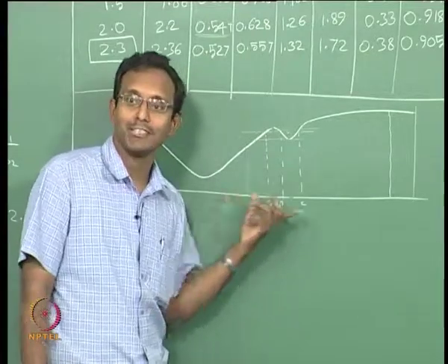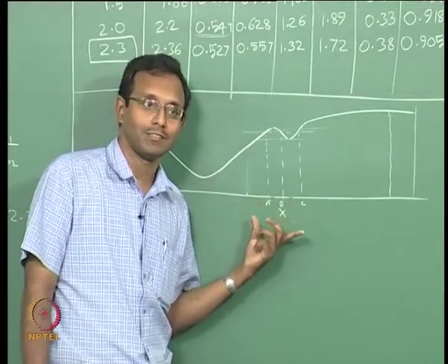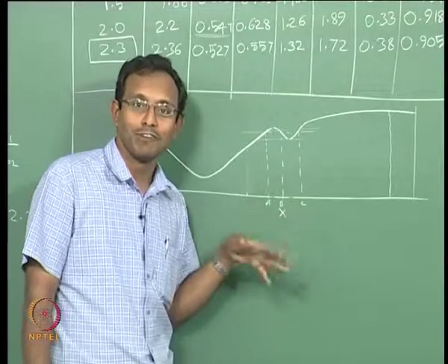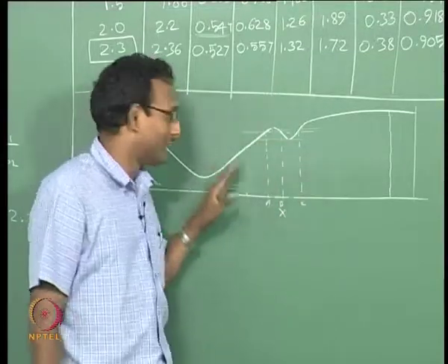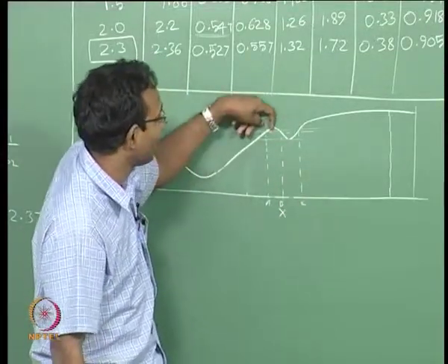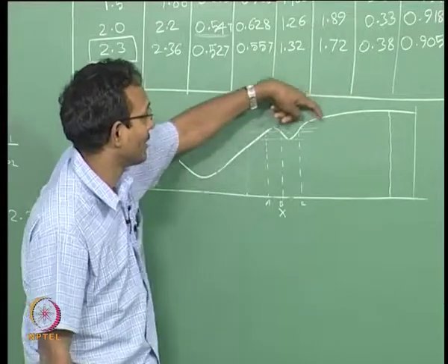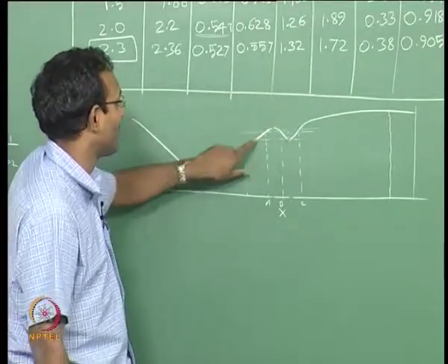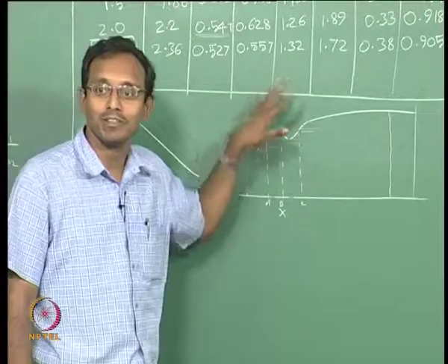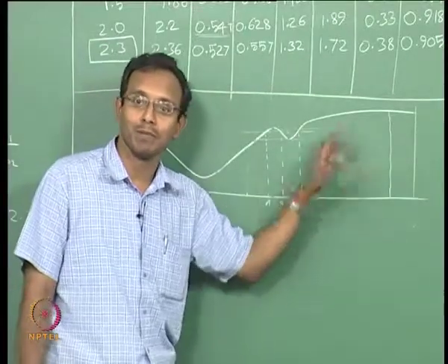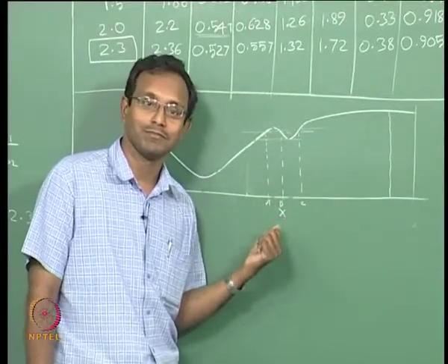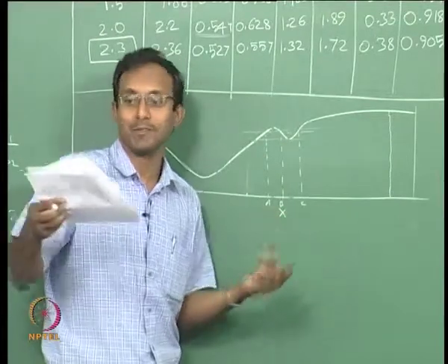So, it is related to the history of the shock. Now, you can think about what if I oscillate up and down. Then my shock will go up to this point, jump to that, go there, and when it comes back it comes all the way till here and then jumps from here directly to here. I will keep on doing this if I keep oscillating my P naught or my PB up and down across this point. That is all fun to think about.